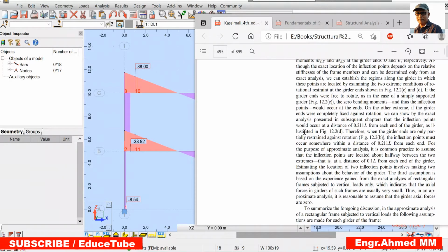inflection points would occur at a distance of 0.211 L from each end of the girder. When is it? If this is fully restrained. Here it is written, girder ends are completely fixed against rotation.